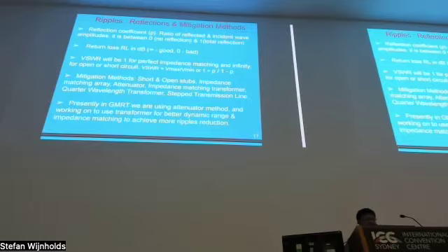These reflections are measured mainly as a reflection coefficient, rho. The reflection coefficient is the ratio of the reflected wave amplitude to the incident wave amplitude. 0 is no reflection and 1 is total reflection. If the reflected power is in watts, then we can use this reflection coefficient. If it is in dB, then we represent it as return loss. Return loss of infinity is good, 0 is bad.